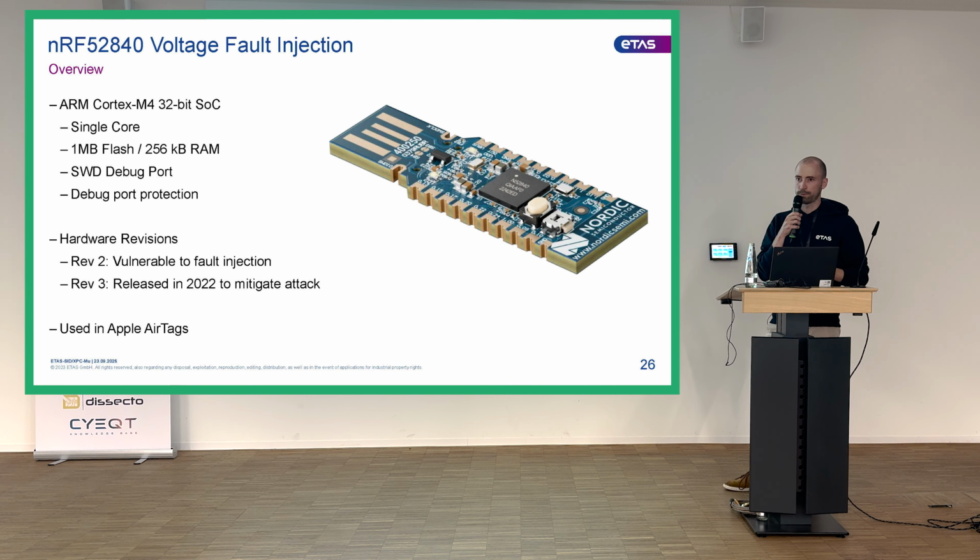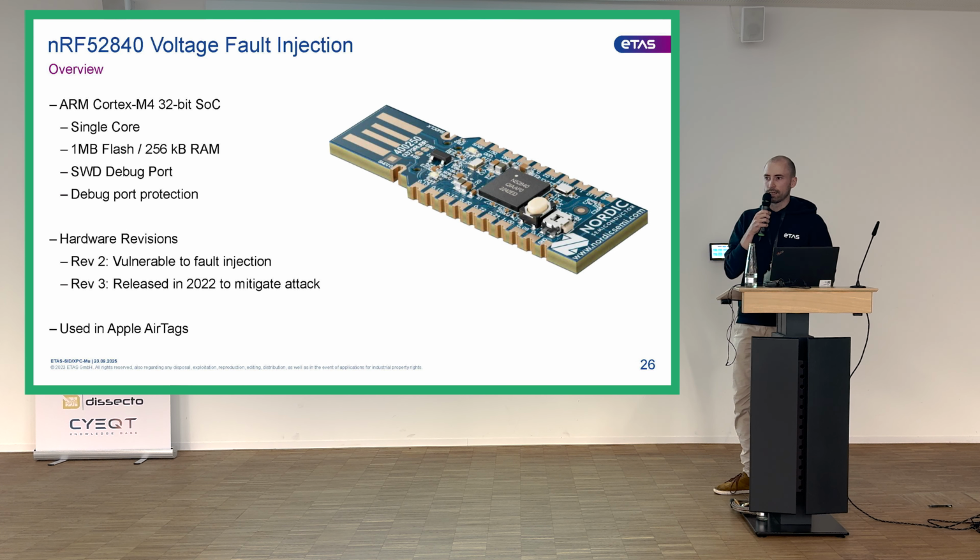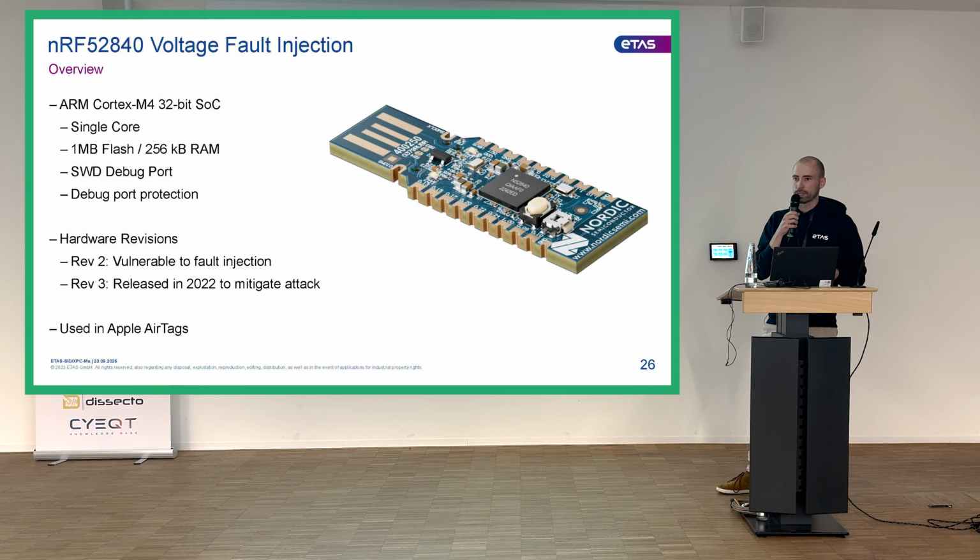And of course, it has debug port protection. So I can lock the debug port, and once it's locked, the only way to unlock it is to erase the chip. So I can erase the flash, and then I regain access to the debug port. But of course, everything that's inside of it is gone. They're used in the Apple AirTags, so they're quite an interesting target for people. There is one revision that's vulnerable to this fault injection, revision 2. They released a new revision in 2022 to mitigate it.